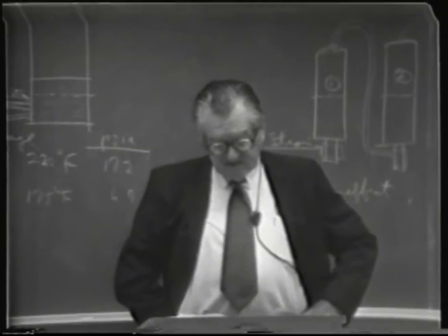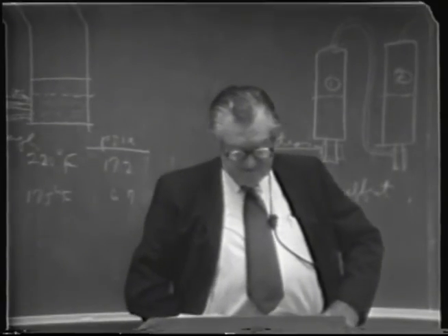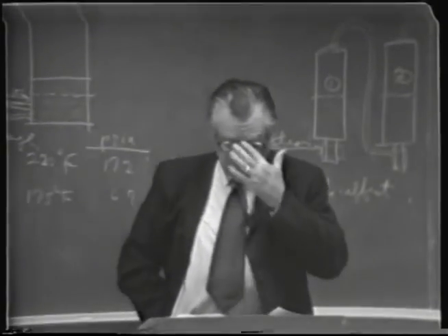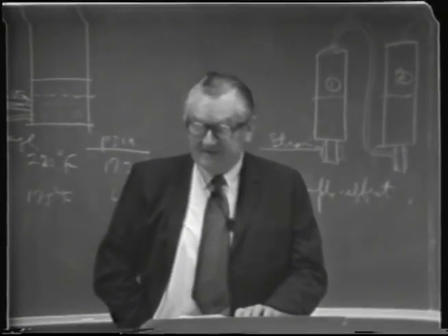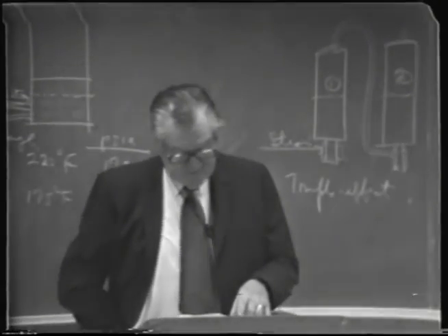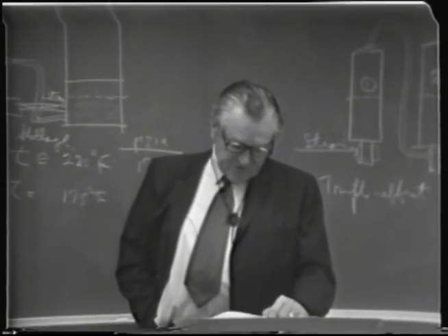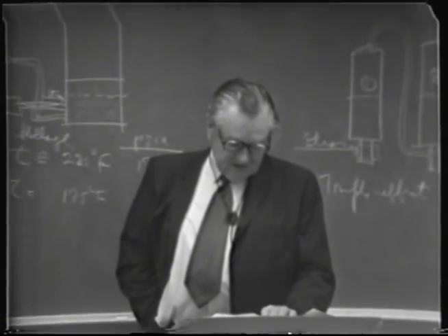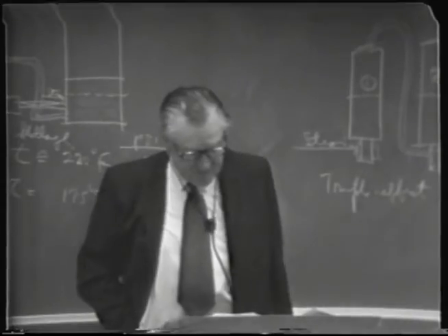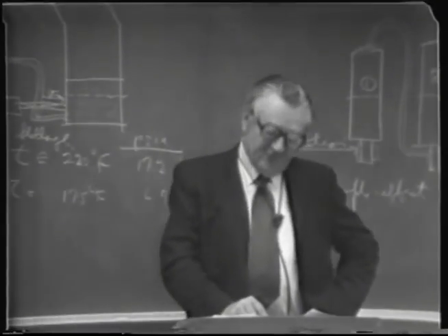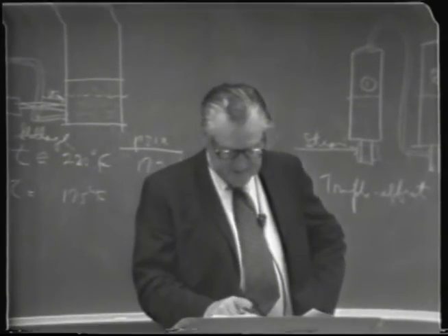column where heads are taken off the top, but the bulk of the alcohol comes out the bottom as a relatively dilute material. The low wines, for example, could be anywhere from 40 to 60% alcohol, or 65, something like that. If you have enough plates, of course, the heads will come off at 192 or thereabouts. So the purified low wines comes out the base, would be somewhat reduced in strength, in proportion to the amount of heads taken off and the amount of alcohol removed there. But anyway, it may come out to be 40% alcohol, 80 proof. Then that's fed into the primary concentrating column,